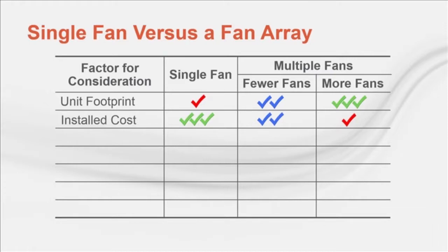When multiple fan wheels are used, the air handling unit can provide some level of redundancy. Of course, this requires proper selection to ensure that when one fan fails, the remaining fans are able to provide the required airflow. In most cases, an array of 3 or 4 fans is able to provide the same level of redundancy as an array with many smaller fans.